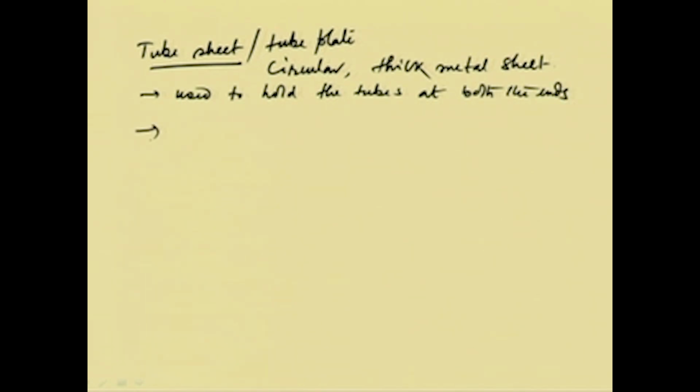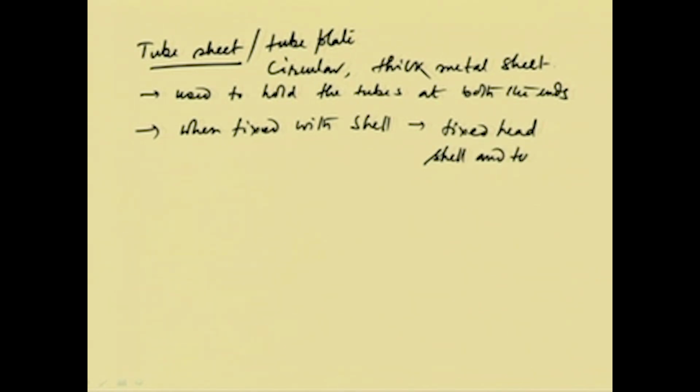Okay. Now, these tube seats can be fixed, or may not be fixed. When fixed with the shell, it is called a fixed head shell and tube heat exchanger, and it may be floating, then we call it a floating head.